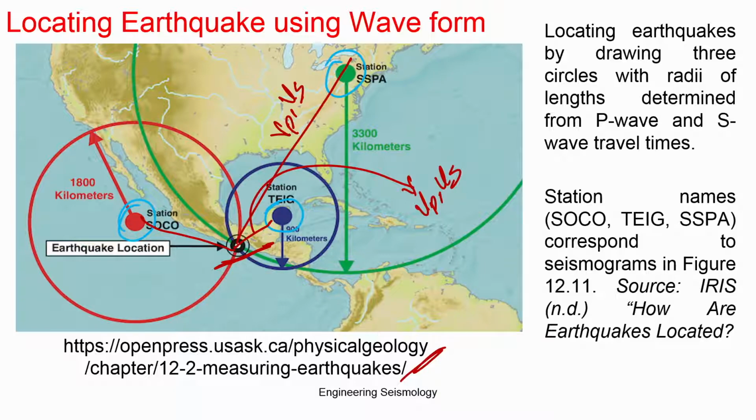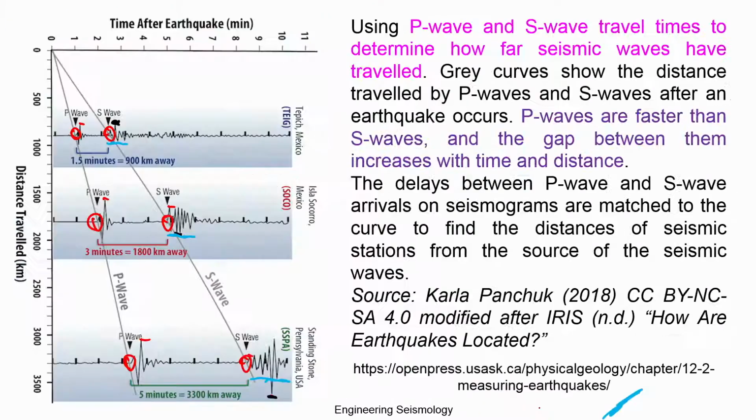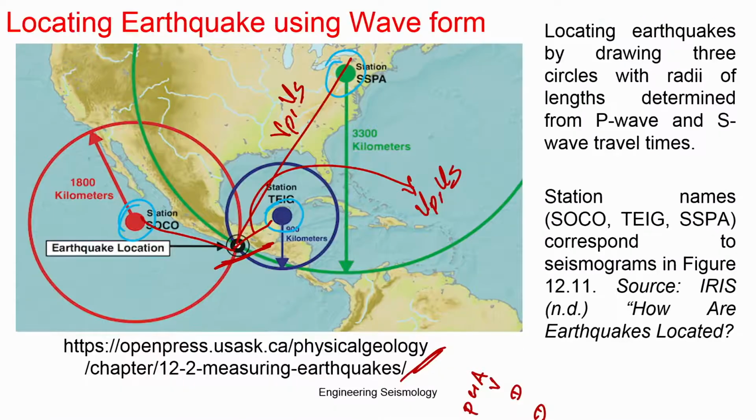Okay. So this is the direct wave, where we can expect the PGA, PGV and PGD, and then the duration, which we have seen here. Depending on the type of duration, your threshold value keeps changing, but this is the data we will predominantly use to arrive at the duration. These details will help you infer from the earthquake data what is useful for engineering applications.